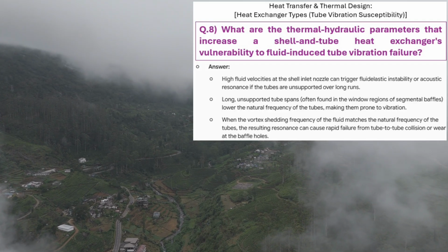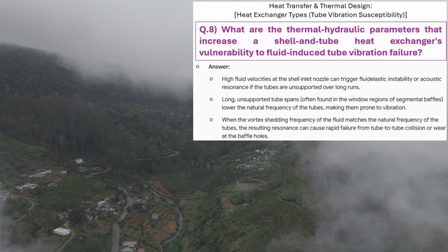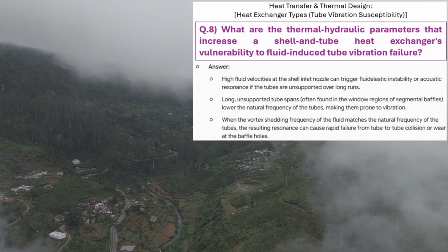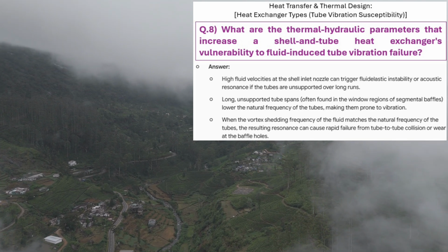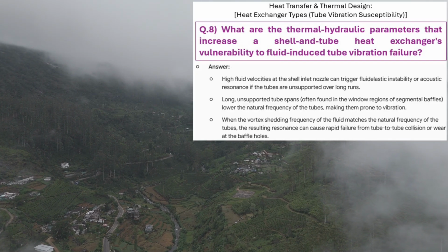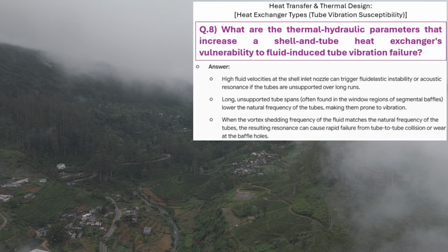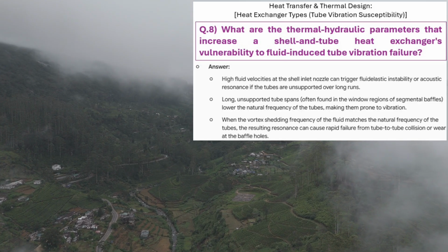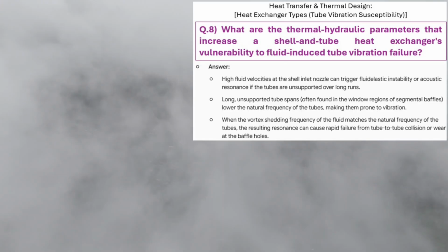A midstream gas-to-gas exchanger underwent a project pushing shell-side velocities up by exactly 30%. The EPC team failed to map the acoustic and mechanical frequencies against the new velocity profile. So the vortex shedding frequency shifted. Yes, it identically matched the unsupported tube's natural structural frequency of 42 Hz.